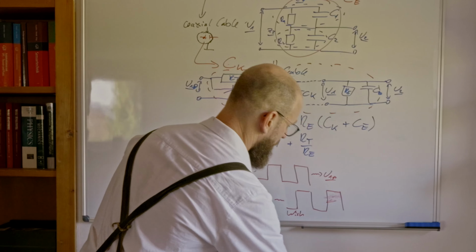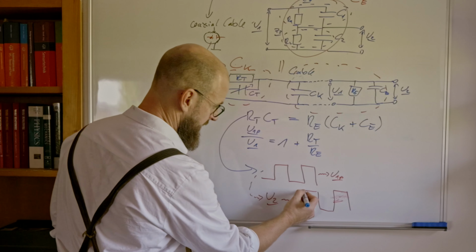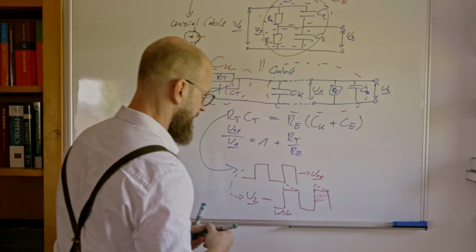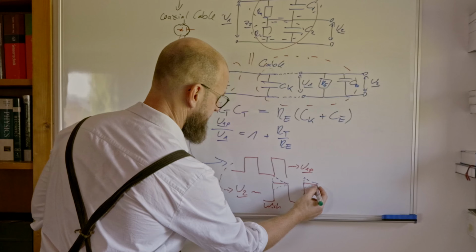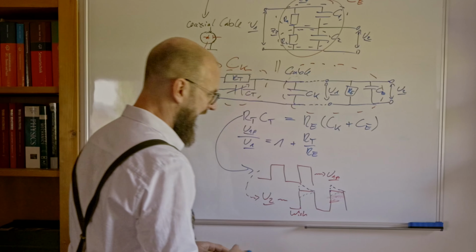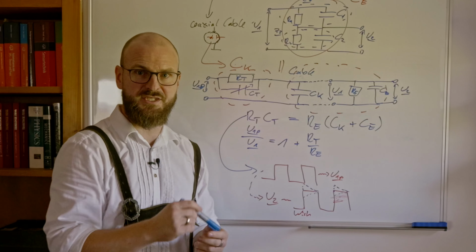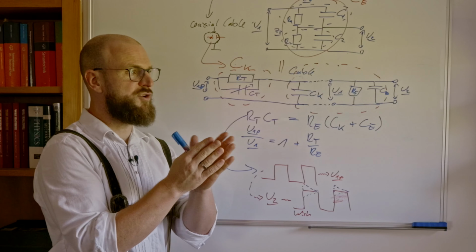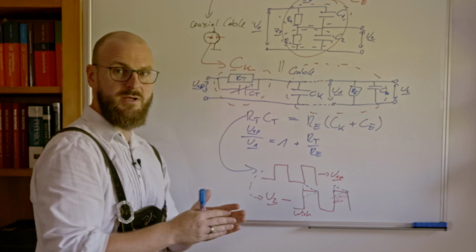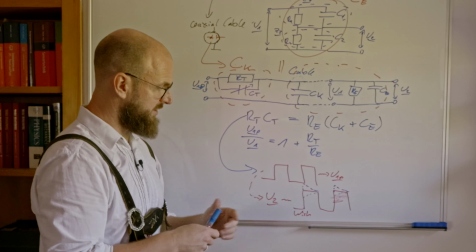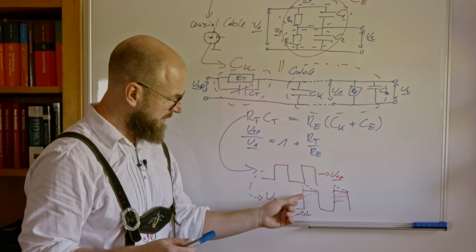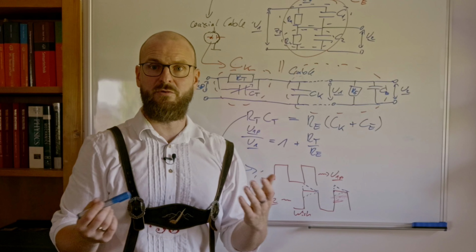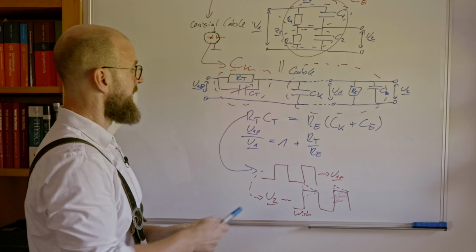But when CT is not adjusted correctly, you will see some deloading or loading curves, which denote that the high frequencies coming along with the sharp edges, the rectangular signal, produce some frequency dependent behavior of the amplitude in your signal, and that is what you see over here. Speaking about electrical circuits, those are loading and deloading curves of the remaining capacitance in the system, of the remaining capacitance which can be loaded or deloaded.